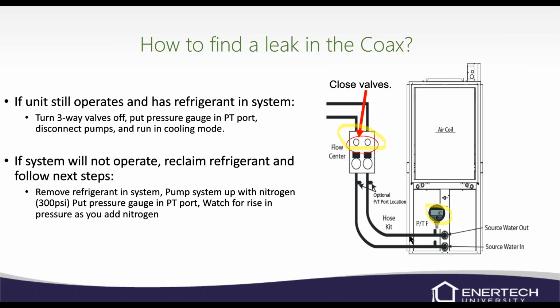When I'm in our model shop testing air coils or heat exchangers, I usually test somewhere about 400 to 450 psi. Sometimes real small leaks, you can't find them at 150, 200 psi. So don't be afraid to put some pressure on there. These systems with the 410, they're rated for almost 1,000 pounds. I think ours are like 850 or something like that. So don't be afraid of blowing something up. It more than likely is not going to happen. I've never had it happen.